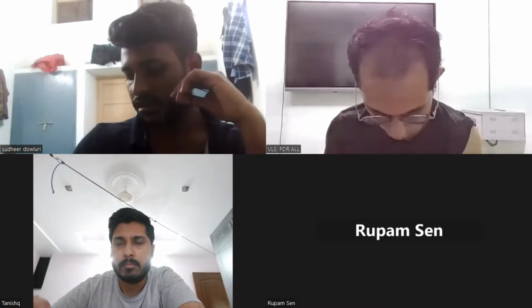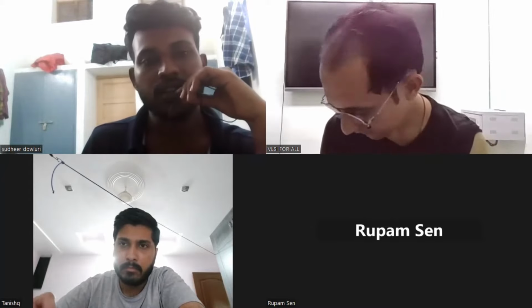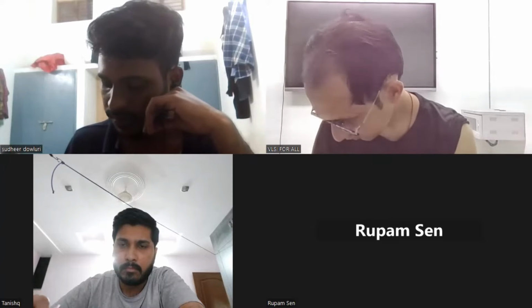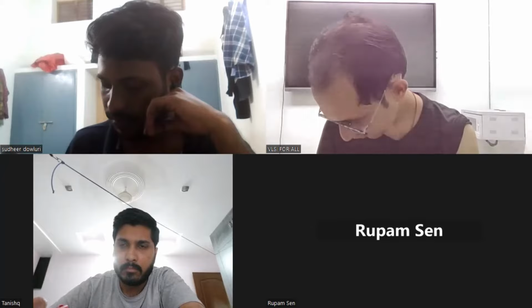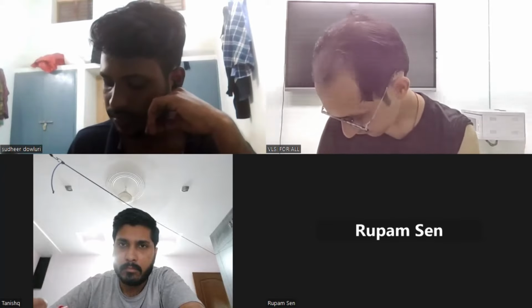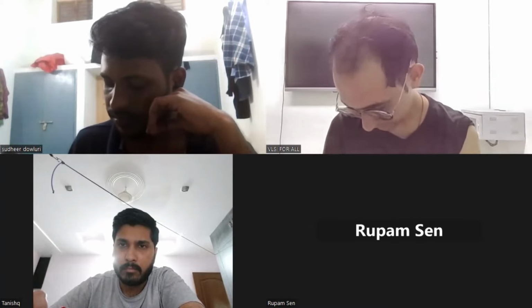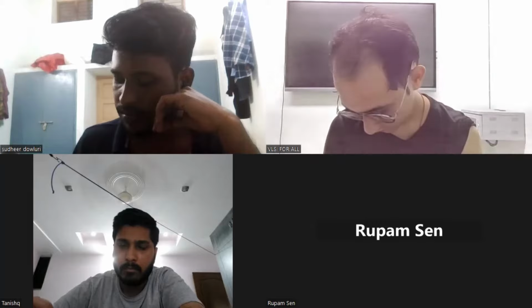Okay. What is correct, right? Who is saying? Rupam, tell me. When both inputs are 1 and we choose a level sensitive clock and the gate delay is less than half of the time period of the clock, then we will face the race around condition.